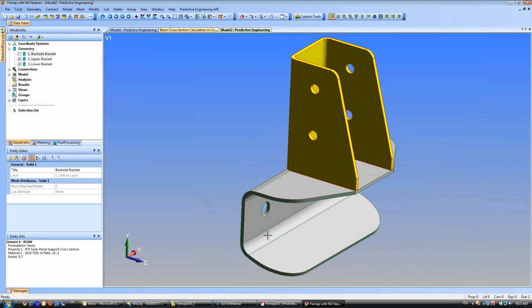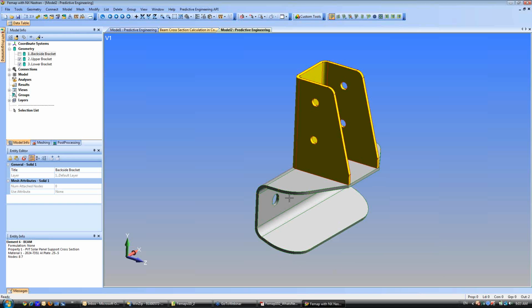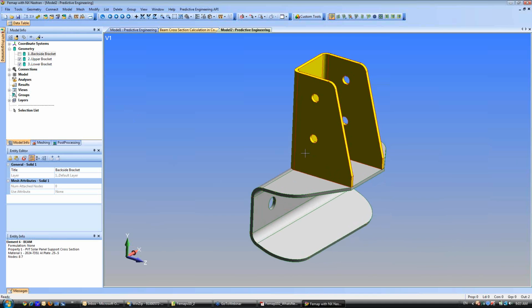Boom. I'm going to mid-surface these things. Okay, where am I going with all this? I'm going to mid-surface it. I'm going to stitch things together. I'm going to glue it into a non-manifold, and then I'm going to mesh the bejesus out of it using all the meshing tools in the meshing toolbox. And then I'm going to analyze it and do some cutting on it. So it covers a lot of surface modeling techniques.